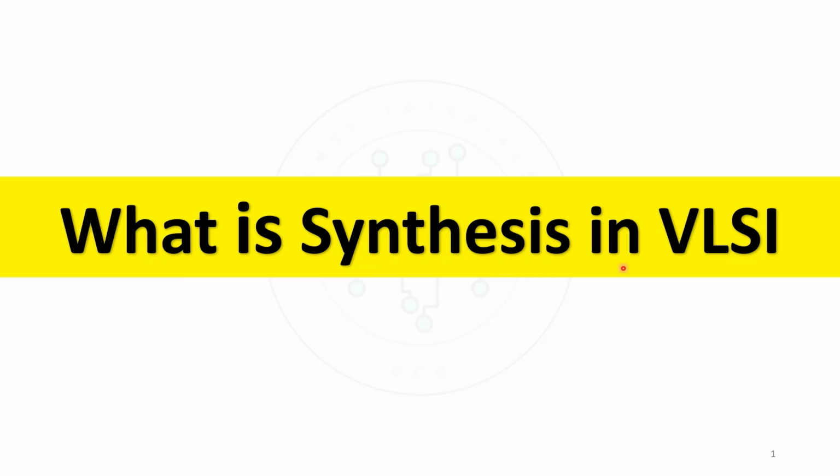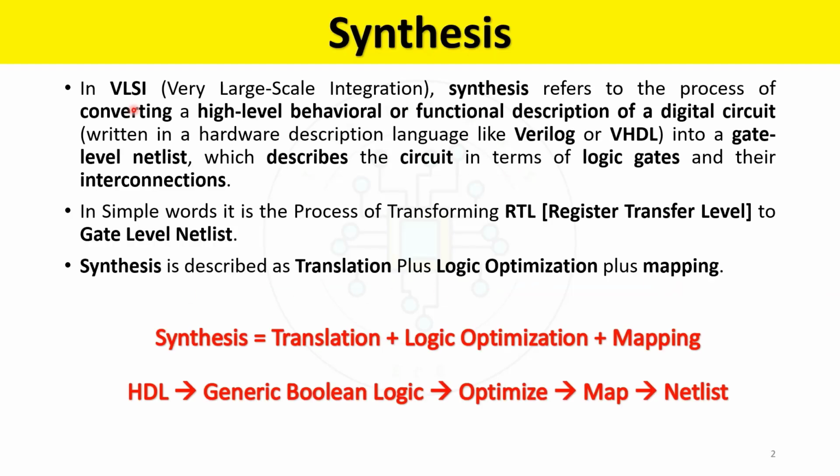Let us see what is synthesis in VLSI. In VLSI, synthesis refers to the process of converting a high-level behavioral or functional description of a digital circuit, which is written in hardware description language like Verilog or VHDL, into a gate-level language, which describes the circuit in terms of logic gates and their interconnection. So, in simple words, it is a process of transforming RTL into gate-level netlist.